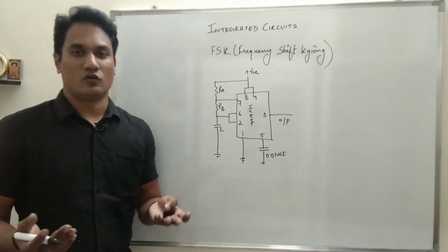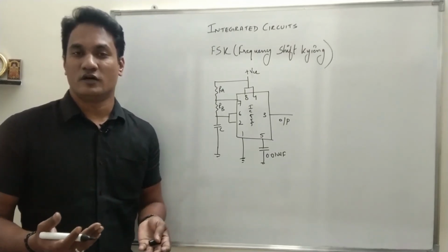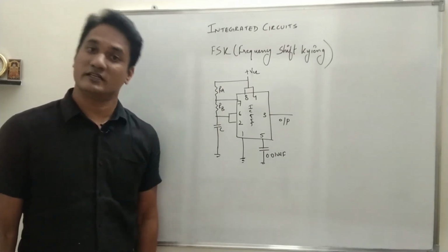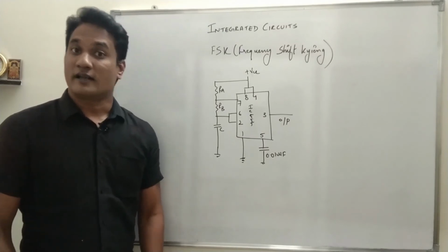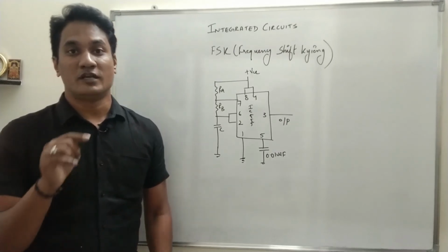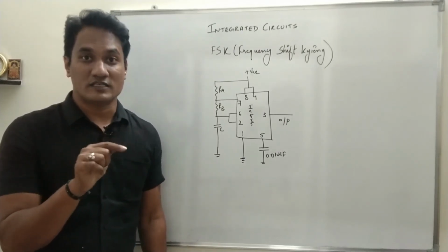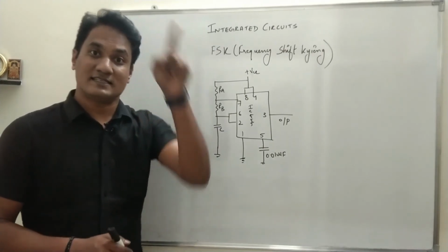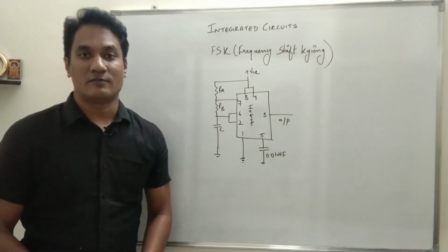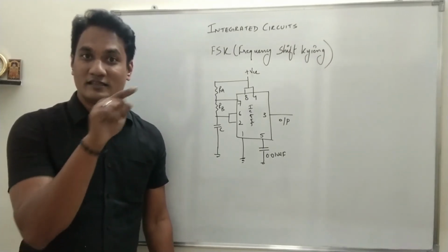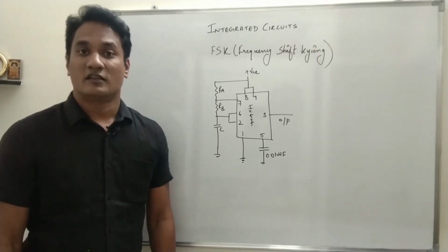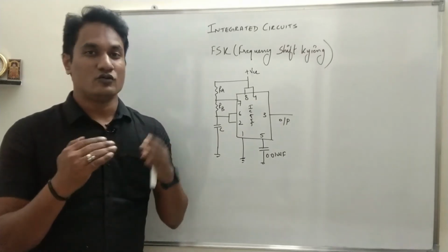Okay, so we have already seen this circuit diagram. We can compare it only with two circuits, either monostable or astable. In a monostable multivibrator, pin number 2 is triggered externally by a push-to-on switch, and pin number 6 is connected to pin number 7. In an astable multivibrator, pins 6 and 2 are connected together, and the potential for pins 6 and 2 is given from the potential across the capacitor. So that is how you have to remember.